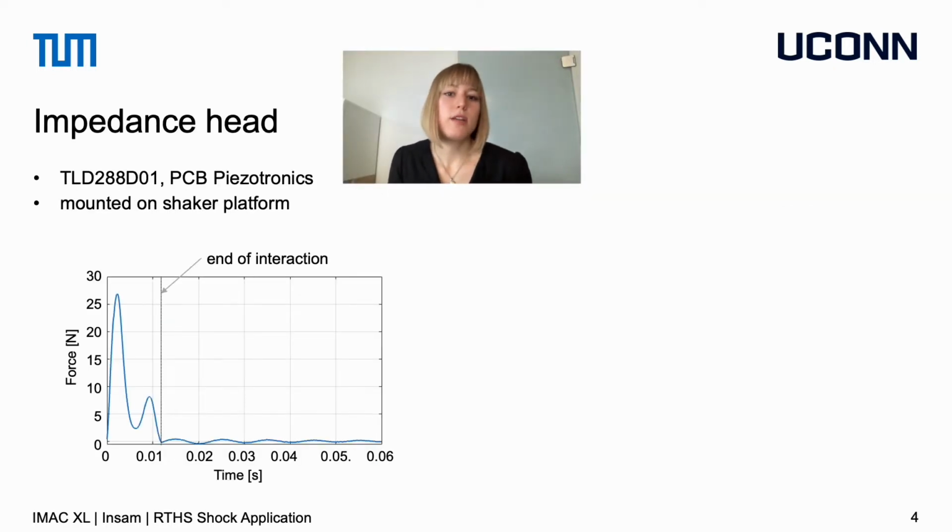The impedance head that we used is a standard sensor by PCB. When we performed an RTHS test with the setup that I've just presented to you, then we see the following measured force. There is a double hump force profile during the interaction period, and the interaction period takes about 12 milliseconds. And after that, we see a small oscillating force.